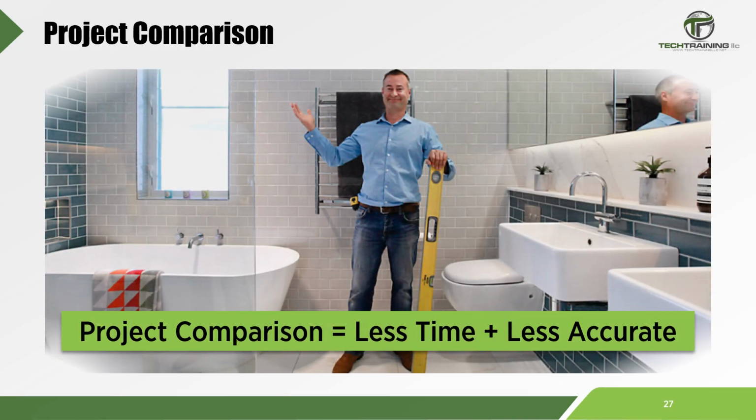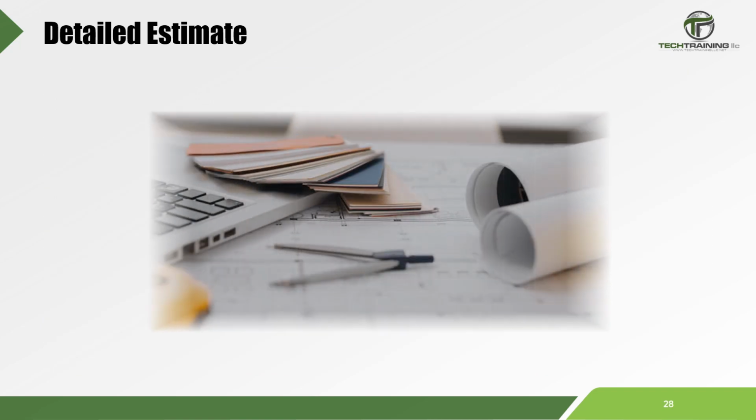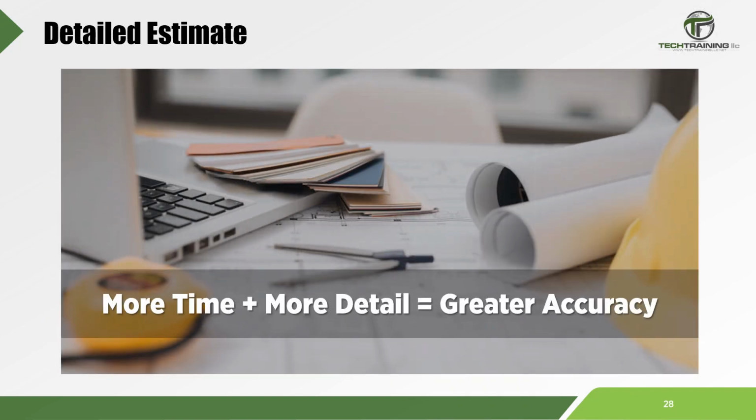As an example, the project comparison method suggests a very quick estimate, but not particularly accurate. Let's assume this would be a bathroom renovation. An experienced contractor would walk into a bathroom, take a quick look around, and say $15,000. Here the 2 represents 2 minutes. But if the same contractor was given information from the homeowner, such as specific tiles, plumbing fixtures, lighting, etc., and requested a detailed estimate, the contractor may take 12 hours and produce an estimate which is almost 100% accurate.